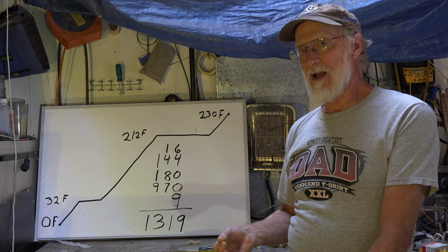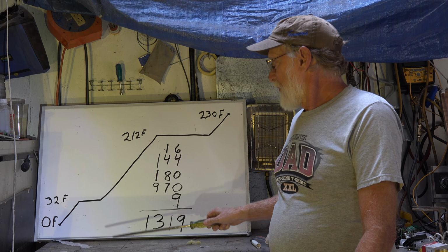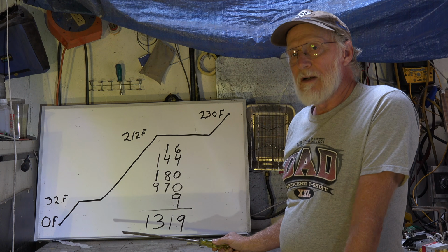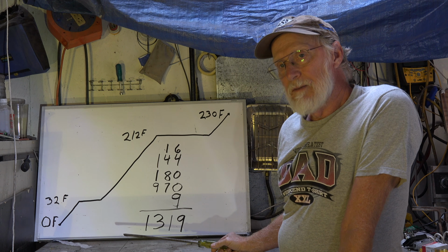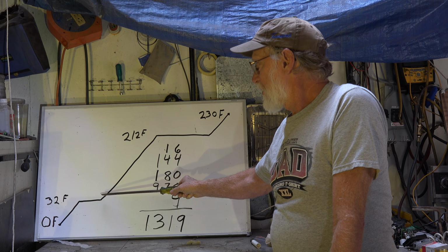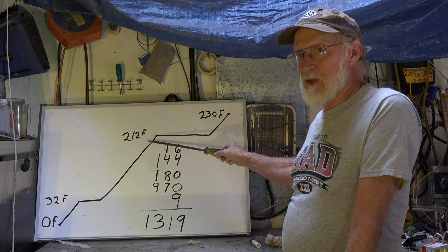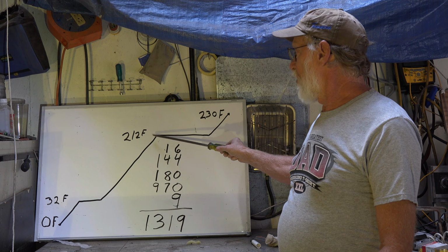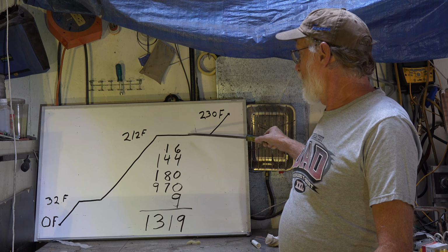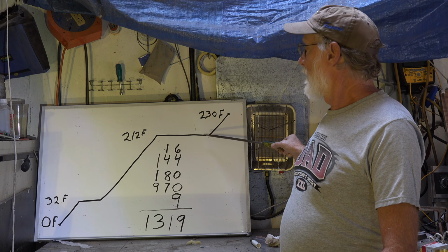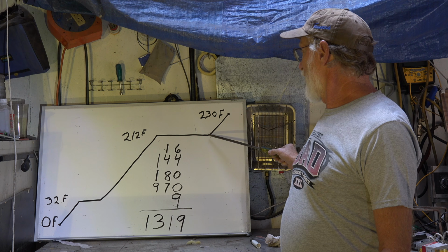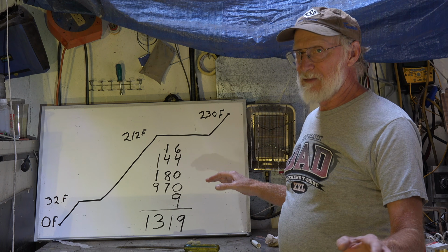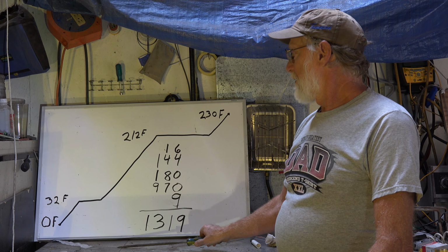Now I just said superheated, didn't I? Well, superheat is something we use a lot of in the HVAC industry. Right here at 32 degrees, if it's turned into water, it's not superheated. Once it starts increasing in temperature, it is superheated. That's called superheat. So this would be superheated water. When I reach 212 and change it all to steam, and then raise this temperature again, now it's superheated steam. And superheat's one of the things we use a lot of.